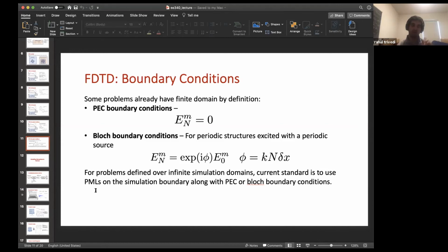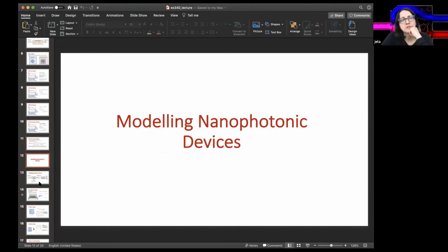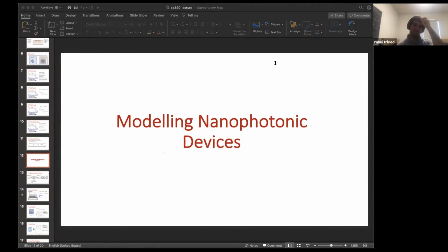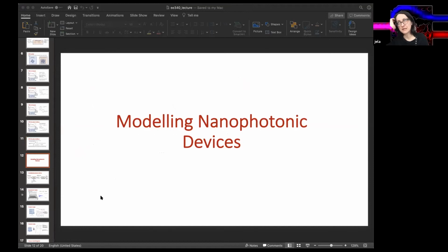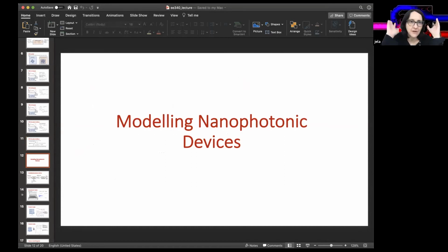Yeah, perfect conductor is not the best choice for pretty much most of the problems. Oh yeah, none of them. What people used to use, what Raul said, absorbing boundary conditions, basically means that you are discretizing the equation for an outgoing plane wave at the boundary, right? If your wave looks like a plane wave at the boundary, then you just write the equation in finite difference time domain for an outgoing plane wave and discretize that equation.